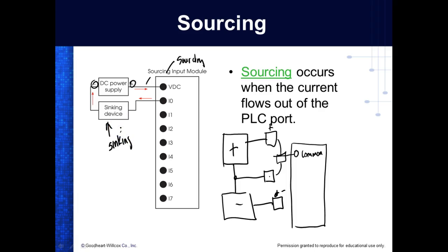So with a push button, it doesn't matter, but electronics will care. If you have what we call a solid state sensor, an electronic sensor, then by George, it's either going to be a sinking sensor or a sourcing sensor. You understand? And if you take a sinking sensor and hook it up to a sinking input, then it's not going to do anything, right?